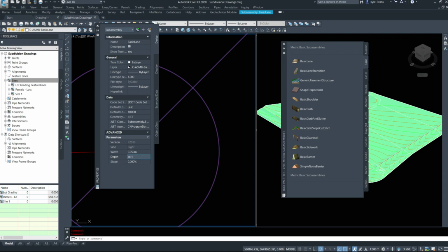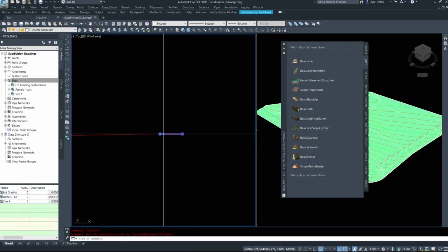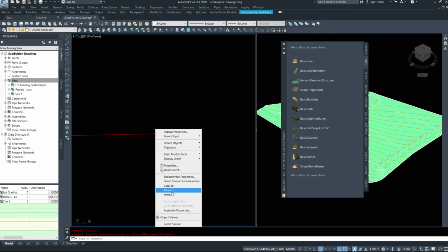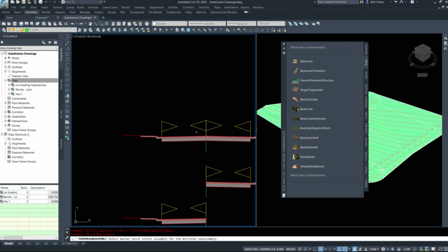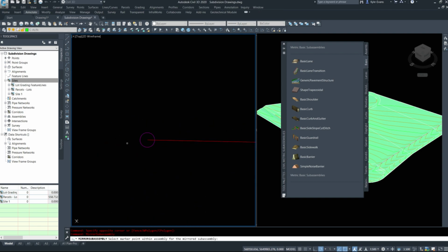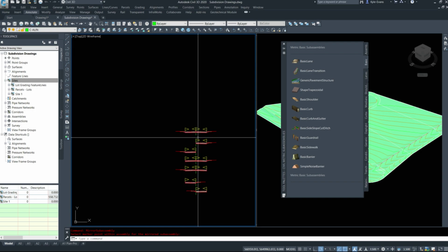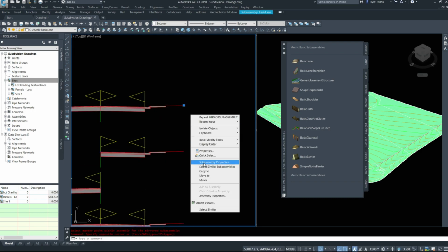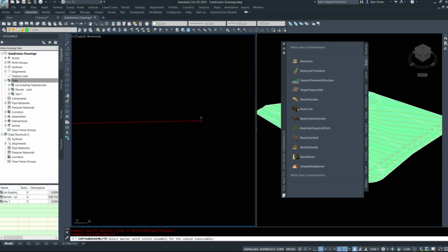Okay, we have to have 0.001 probably. We have to have a millimeter thickness. Yeah, and that'll work. So this will basically extend our corridor on both sides so that they overlap with the feature lines, and we can pull automatic information from the feature lines themselves. Just a tiny little step that's going to help us immensely.